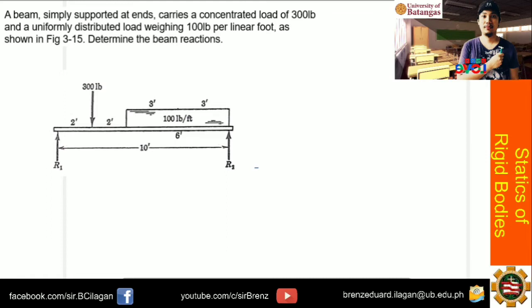A beam simply supported at the ends carries a concentrated load of 300 pounds, 2 feet away from the first support, and a uniformly distributed load weighing 100 pounds per linear foot. So this is how it is shown. But normally, the uniform load looks like this, with all arrows pointing downward. This means that in every foot, you have 100 pounds. Since it covers 6 feet, this 100 pounds per foot can be replaced by a single concentrated load, like this 300 pound load.